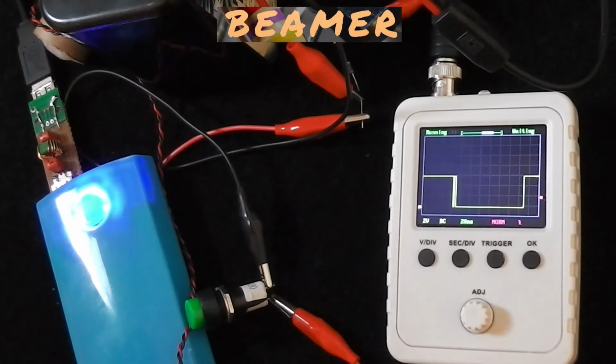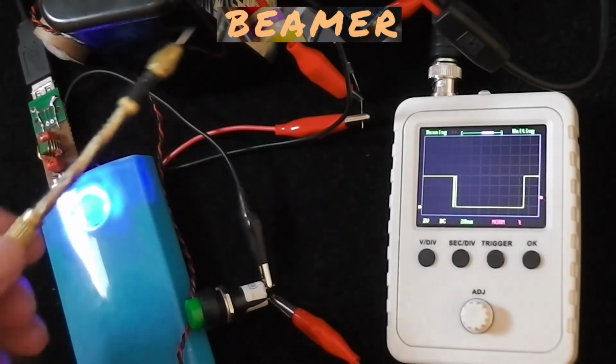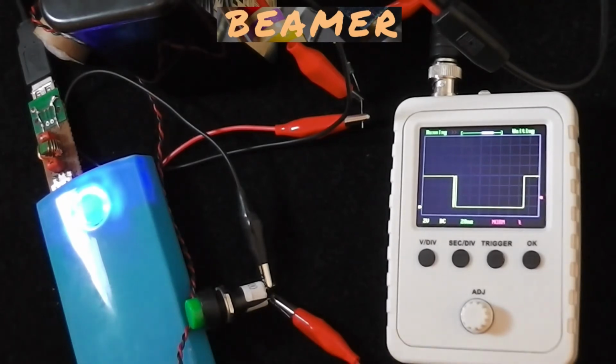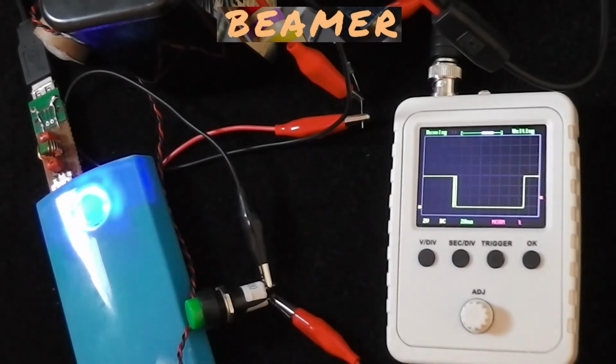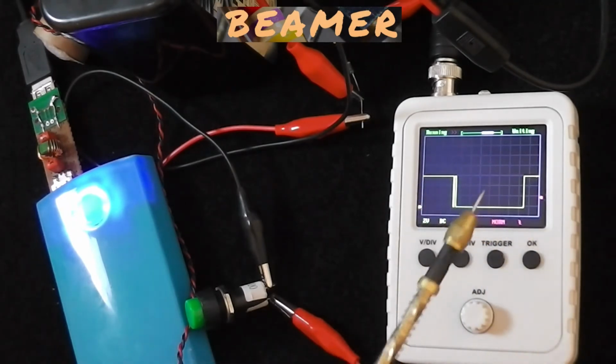Now the setup is the earth, or 0 volts negative, of the battery goes to one side of the switch, the positive of the battery goes to one side of a 4K7 resistor, the other side of the 4K7 resistor goes through to the other side of the push switch, and the DSO goes literally across the switch itself, so that it's going from the positive to 0 volts or negative. And that's what you see on the waveform there. That's the +6 at the top there, and that is 0 volts at the bottom.